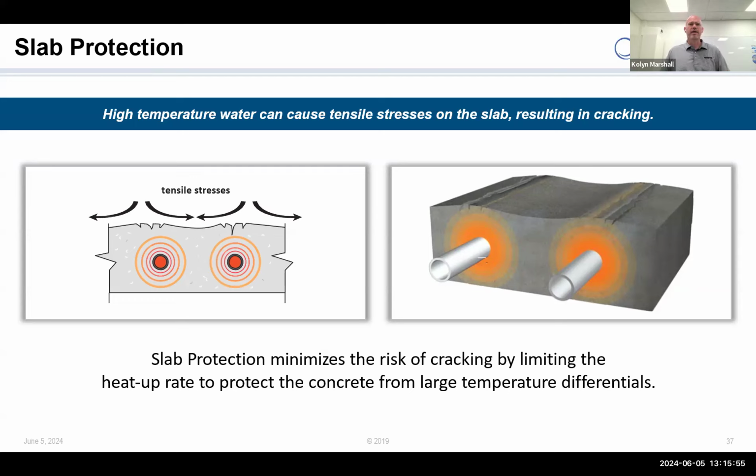Either way, if we keep the water temp and/or wire temp below 150, we're guaranteed not to have an issue. Hydronically, though, I have seen systems run hotter than 150 with no issues.